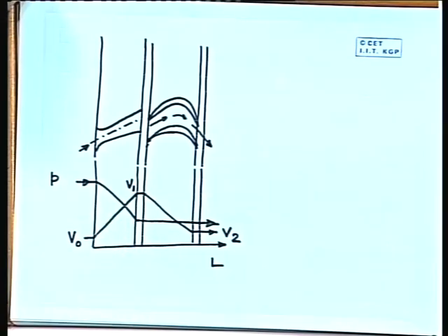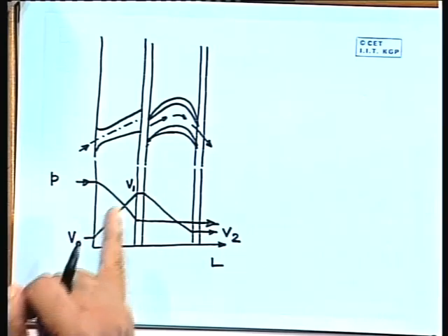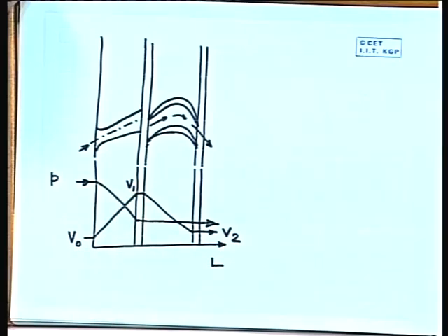And we have to remember one thing, that the blade passage is not a stationary passage, all the blades are moving. So, the velocity which I have denoted here is the absolute velocity of steam which is entering the blade passage and which is leaving the blade passage. So, this is one way of representing how the velocity is changing through the blade passage. There is another way of representation where we can see in a very clear cut manner how the velocity change is taking place in an impulse blading.